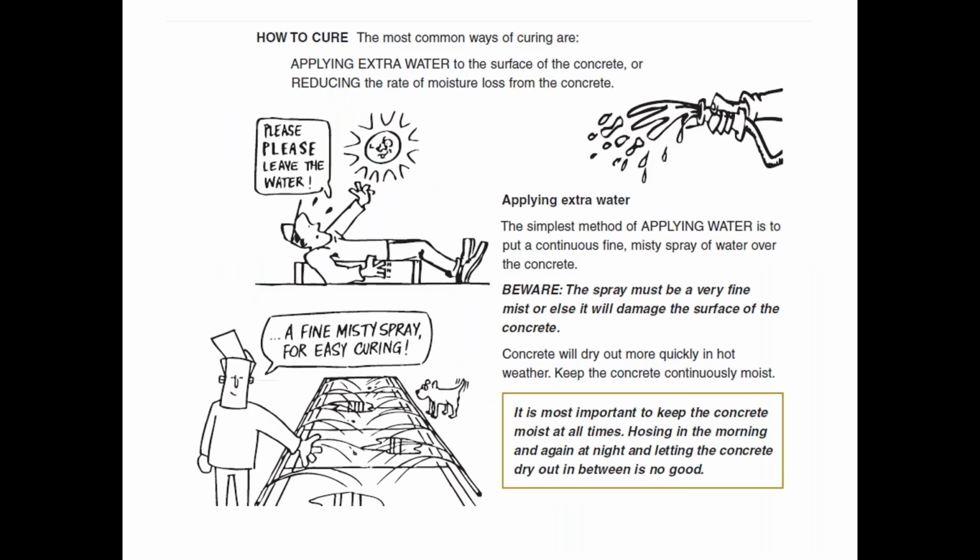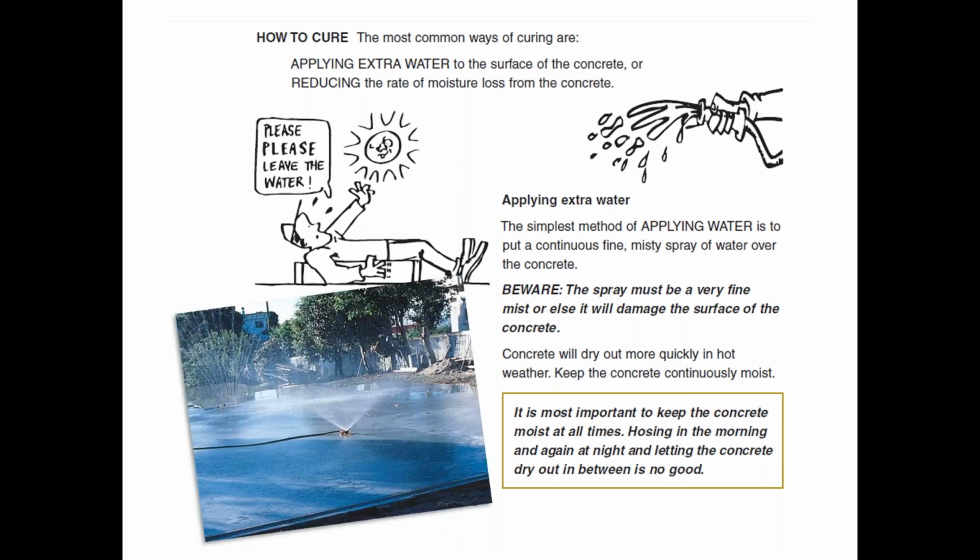So the easiest way to cure is just with either a sprinkler or a sprinkler hose and a very, very fine mist. And here's an example here. Just keep it damp. That's all you've got to do.